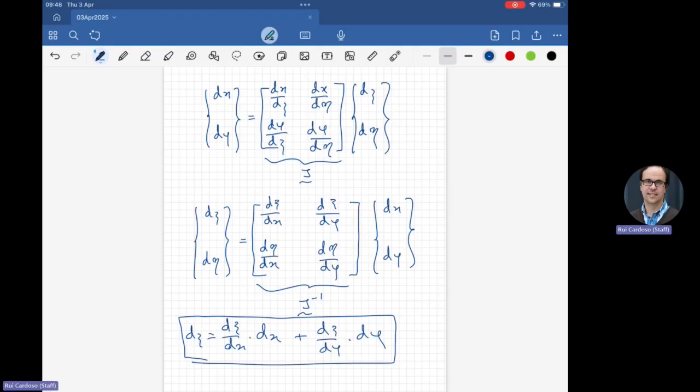Now what we are going to do is build the Jacobian, implement these for loops to get the Jacobian in MATLAB, and then ask MATLAB to invert the matrix for us. So that second matrix that you put there is just something that you did yourself. That matrix is not a real thing. That inverse J to the power of minus 1 is just from yourself. There's no real physics. Yeah, this will be the inverse of the Jacobian, at the end of the thing.